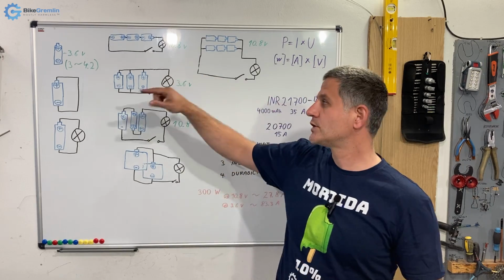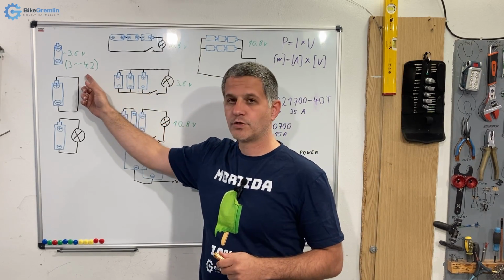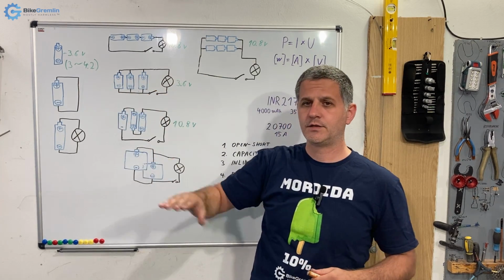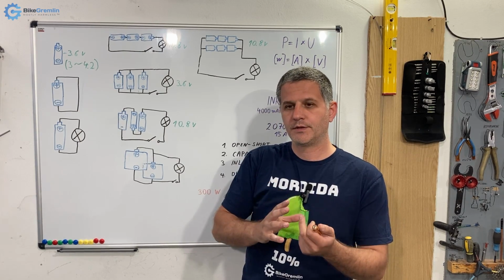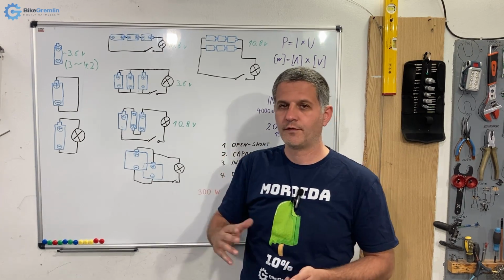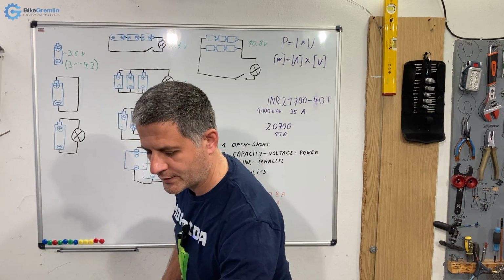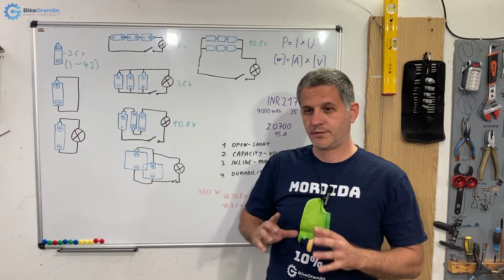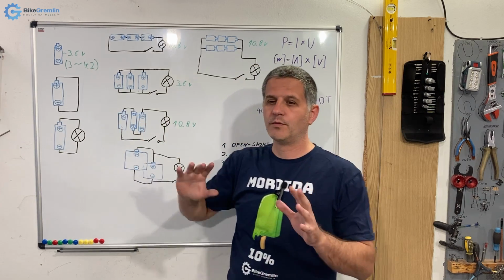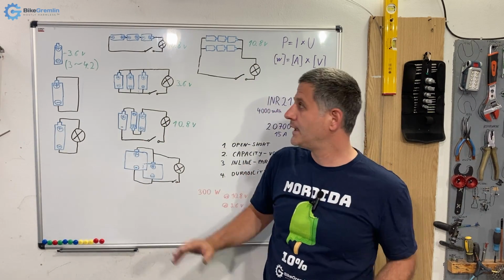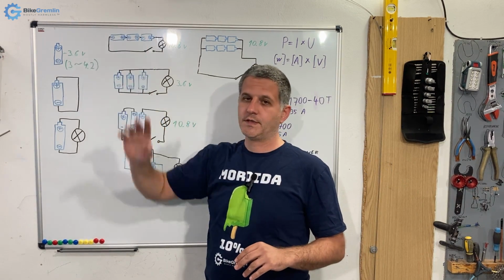Those cells that I mentioned have a maximum safe voltage of 4.2 volts. If you exceed that, you will get some heat, maybe damage, bursting, burning, catching fire and similar. So smart high quality chargers will prevent that. But the nominal voltage that we will use is some sort of average. Let's say it will be 3.6 volts.